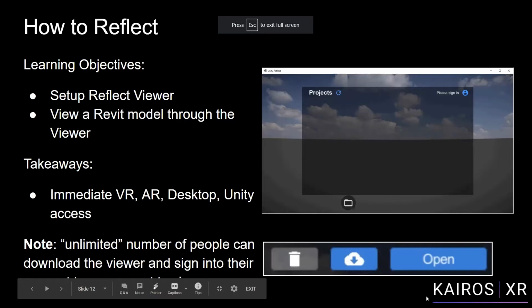Here's our live sync button. And here's a filter feature. So what is live sync? Again, I already mentioned this, but if you make modifications to your file in Revit, we want those to be reflected in our project immediately. And when we toggle live sync on, though it slows down the performance, it brings in those changes immediately.